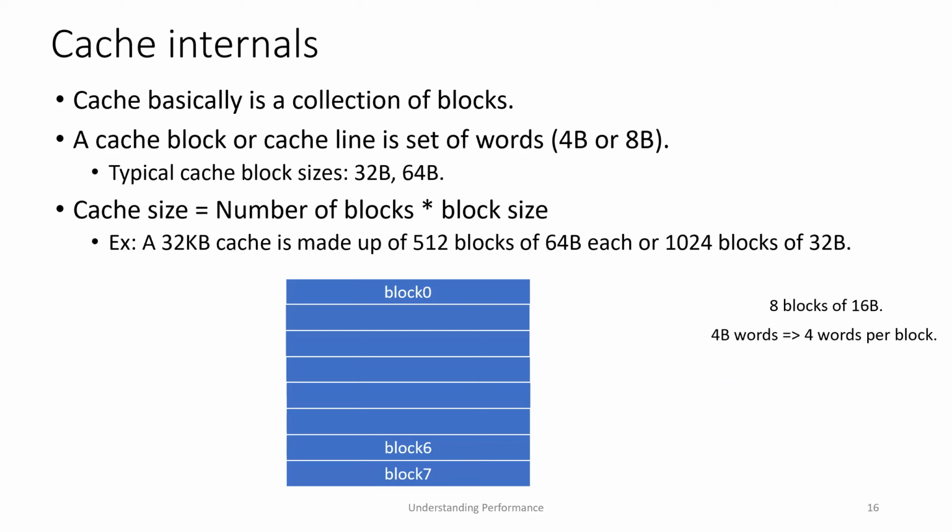Each block has a capacity of 16 bytes, meaning that it can hold 4 integers, for example. Word 0 is one integer, word 1 is another integer, then word 2 and word 3. Each word is a collection of 4 bytes, so it will have byte 0, byte 1, byte 2, byte 3, and so on and so forth.